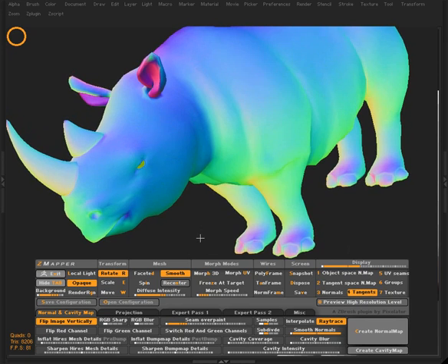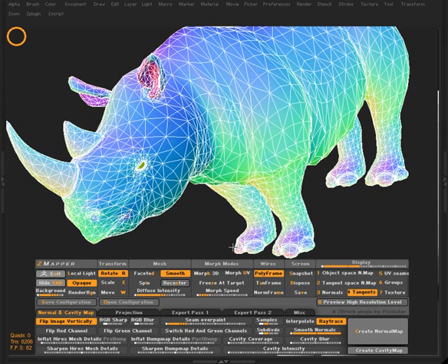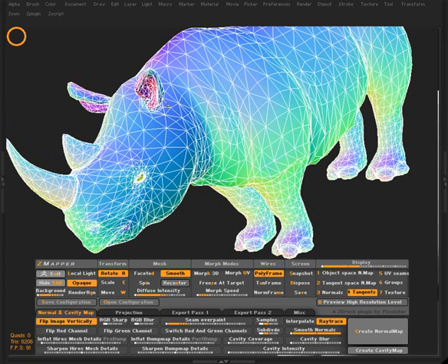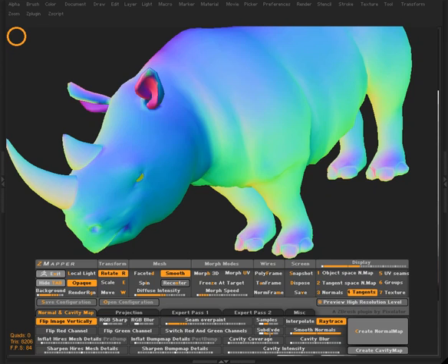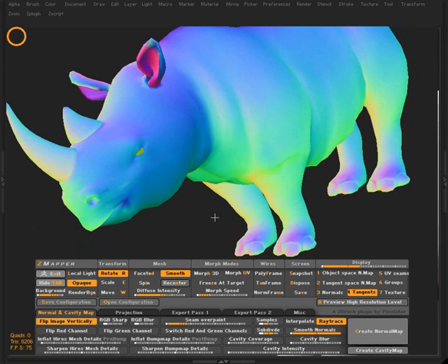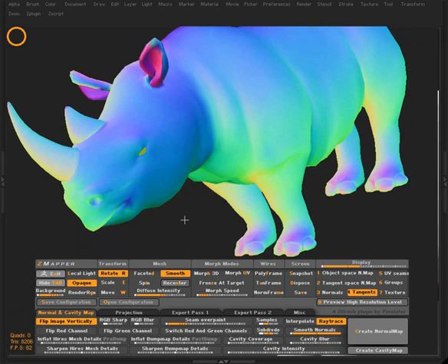So if I were to take a look at the wireframe of this object, you can see that we wind up with a lot of these different squared off areas, and unfortunately if we calculate the normal map at this point, the normal map will have some of these edges where we have the UVs. So to fix that, if we take the actual subdivisions up, that will help smooth out the overall subdivision result, or the normal map result. So usually I try to find myself setting this up around 2 or 3 subdivisions to get a nice result.